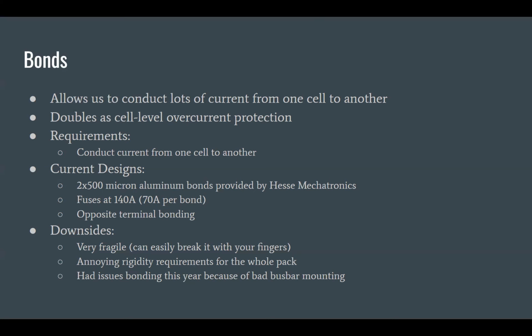And so there's a box basically that it all sits in, and then the idea is that the holes in all of the interior walls are lined up. So air can flow through the steel wall, through holes in that, out through another steel wall into another segment, so through the battery pack cell, through the box, and then back out of the other side of the pack. And then we have fans that push it.